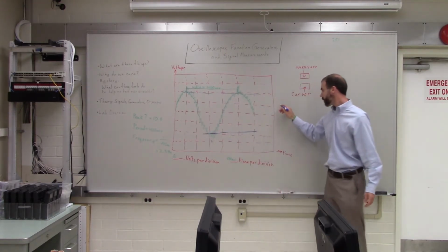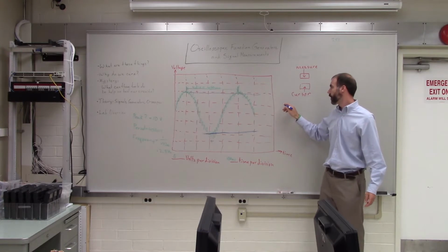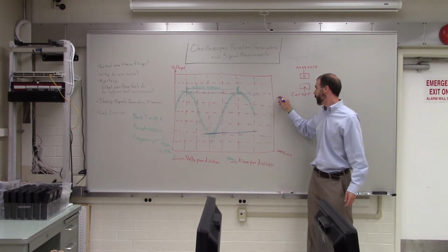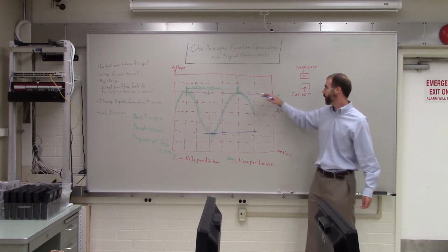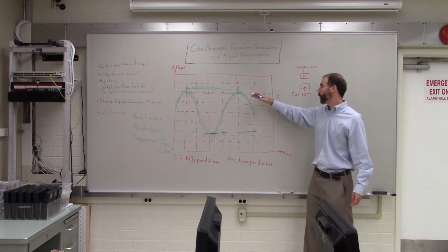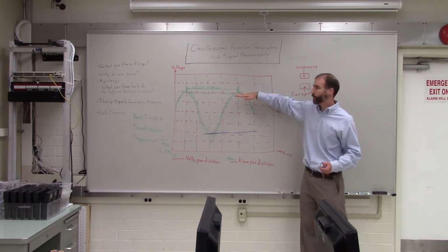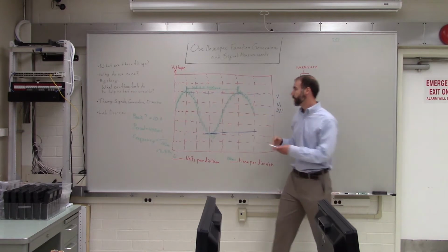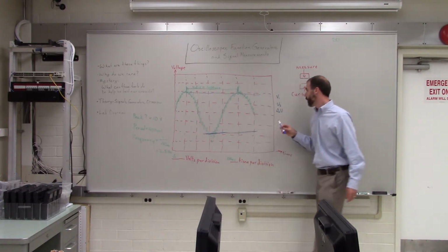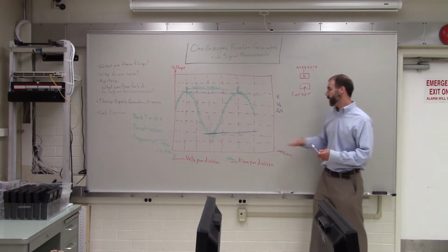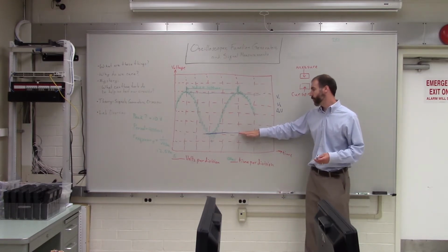And then over on the right-hand side, it gives you 3 pieces of information. So it gives you V1, V2, and then delta V. Okay? So V1 is the voltage for cursor 1. So that would be like the position of this top one. V2 is the voltage for cursor 2, so that would be like the voltage of the bottom one.